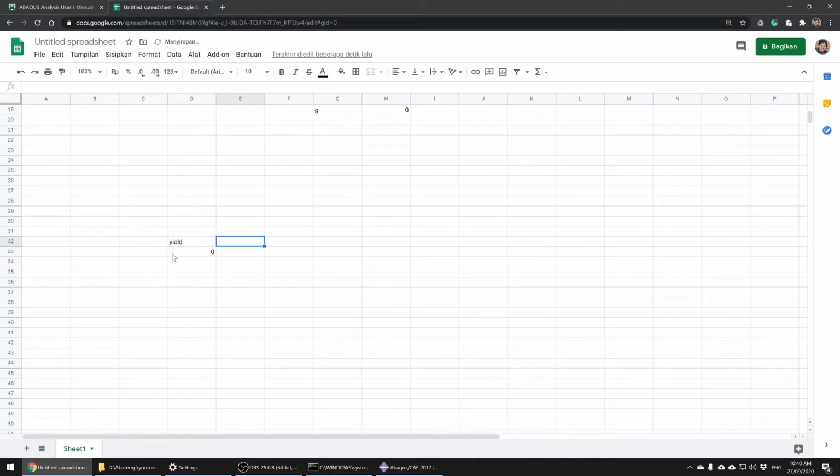This is not really fake, but because the value will be related to epsilon p. When the plastic strain is 0, it means that during the beginning of the yielding, the yield strength is 20 MPa. During 1%, they are 25. And then during 5%, they are 30. Okay, so this is the hardening curve.